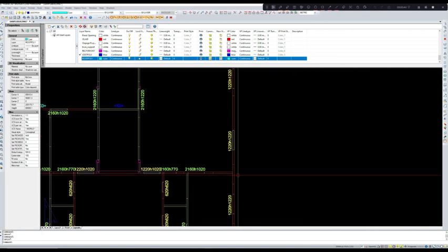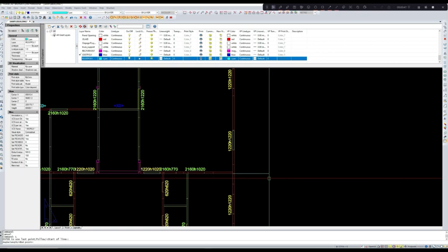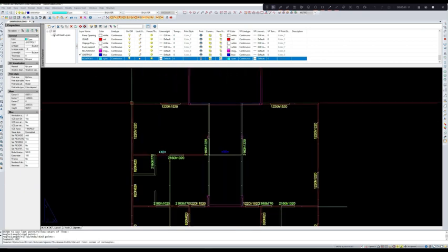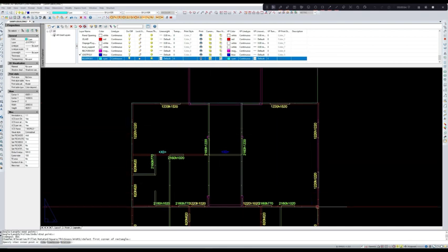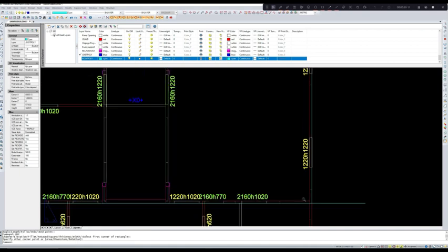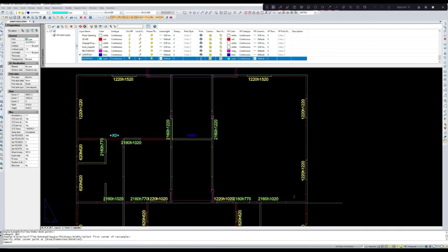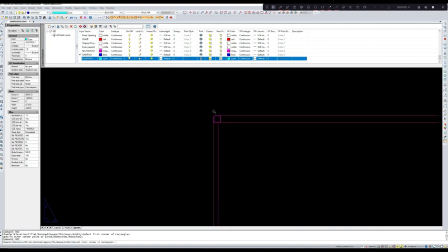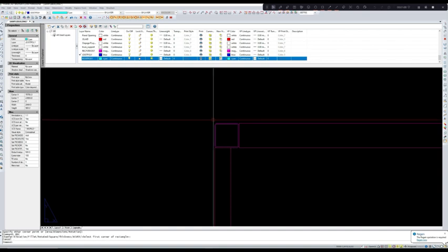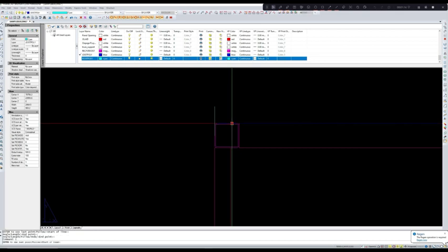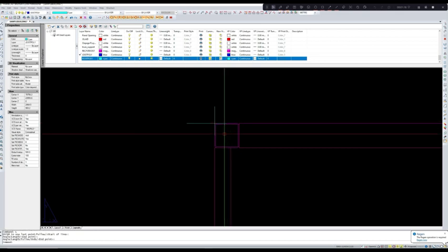Now before that, we need to draw a line here, so let us make the required rectangles which will be required for us to create the roof. Now this is one rectangle, then this is again, here also we'll need some line. This is the rectangle command again.